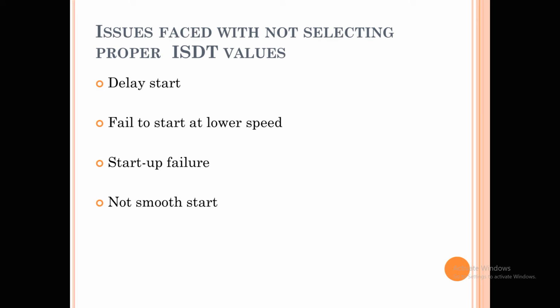So in that case, if your delay is very high and it looks annoying to you, then you need to reduce the time of that particular setting. Okay, to some extent you may not be able to tolerate a delay, but at the same time it should not fail to start or go for a jerk start. So the first point: if you face any delay in the startup, you need to reduce the time duration of your ISD setting.